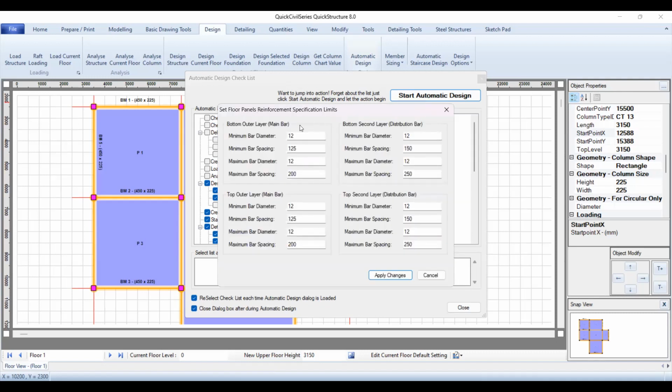Then I said, for floor settings, my floors obviously we use Y10 and Y8. So I make sure all are Y10. It doesn't mean I'm designing for this software. I'm just giving it what I have in the market, what I want to use, so that you can use that to design. You'll do the other design. So I decided to use Y10. I don't want to use Y12 for slab.